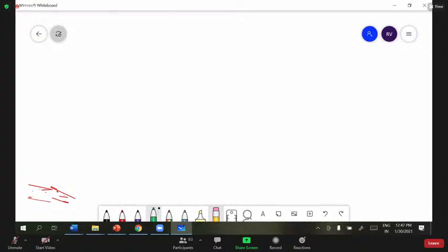If you know K-map simplification, if you know the excitation table of the JK flip-flop, you can easily design this synchronous counter. These synchronous counters are used to count even random sequences. In the exam, they will give you a random sequence. You should be able to count that random sequence also based on that.